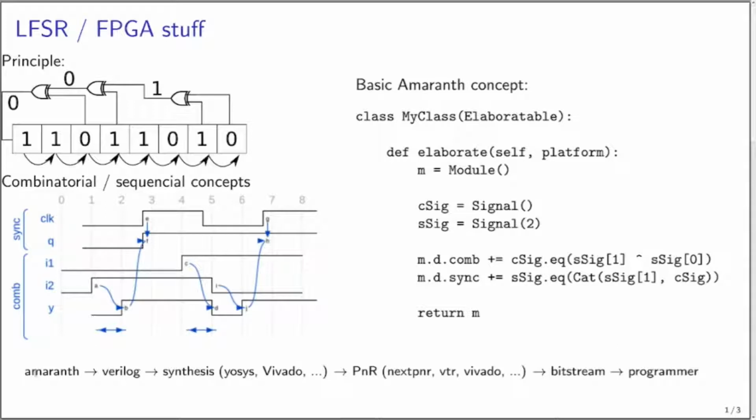So the first thing done by Amaranth is to produce a Verilog equivalent of the gate array written in Python. This Verilog is used as an input by the synthesis tools to convert some parts, for example the XOR, to LUTs or to specific primitives for the targeted FPGA. The result of this first step is the input of a second step, placement and routing.